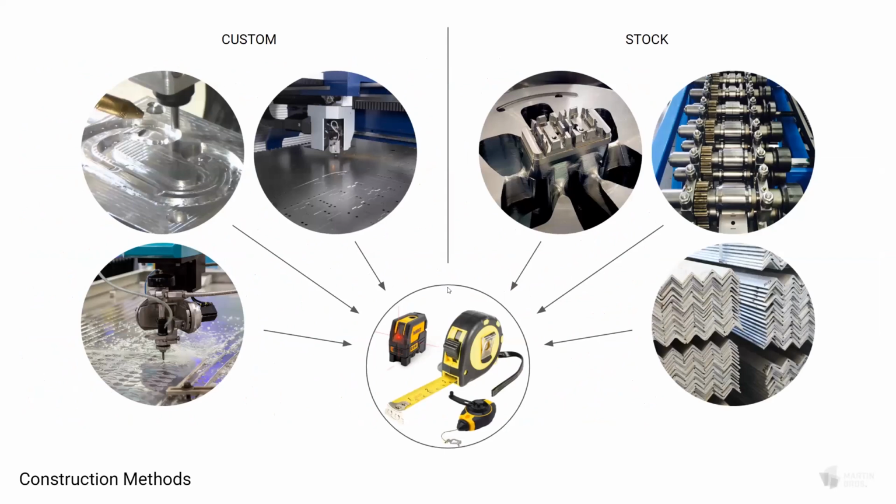We're achieving mass customization more cost effectively by strategically concentrating the variability in certain components, which are then custom laser cut or milled. This allows the rest of the components to be very standard stock commodity elements. And the consistency afforded by this system makes each frame much, much simpler to assemble, because at the end of the day, our field team, a human, has to build this with their hands. A measuring tape, laser level, chalk line, that's pretty much it. As an added bonus, the consistency also allows us to fully automate fabrication and assembly drawings.